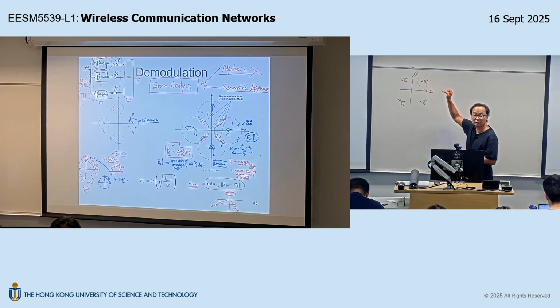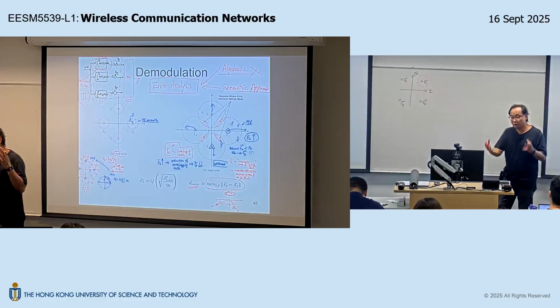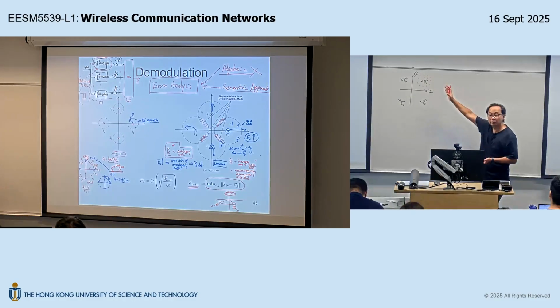As we have explained the mechanism. And let's assume this is a small noise scenario, so the size of the noise cloud is pretty small. Now, let's say I transmit S1, and let's say this is my current observation. We will always be using minimum distance demodulation. Now in this case, what will be the output of your receiver?